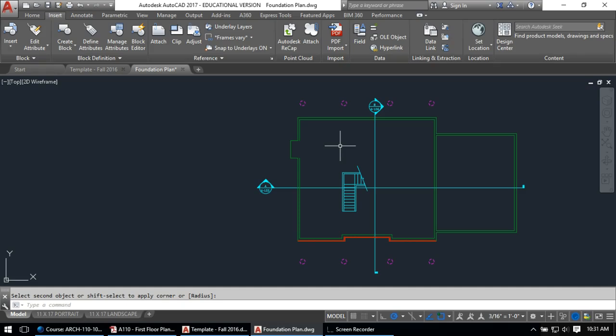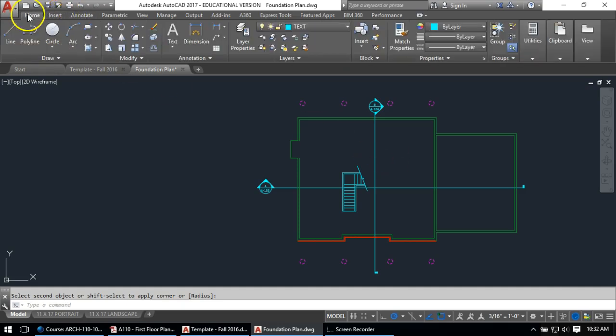So that's why a lot of times, especially in residential construction, you see so much of the dimensioning happening to the center points of these elements. It's to help the construction process, to give leeway for all these slight variations that might come up along the way. Of course, that makes it a little more difficult to draw in AutoCAD, because we have to draw center lines and then offset them to get the edges, but that's the way it is. So that's what we'll do, and I'll basically just go through and start dimensioning and offsetting, drawing lots of construction lines and various other techniques to get this done.